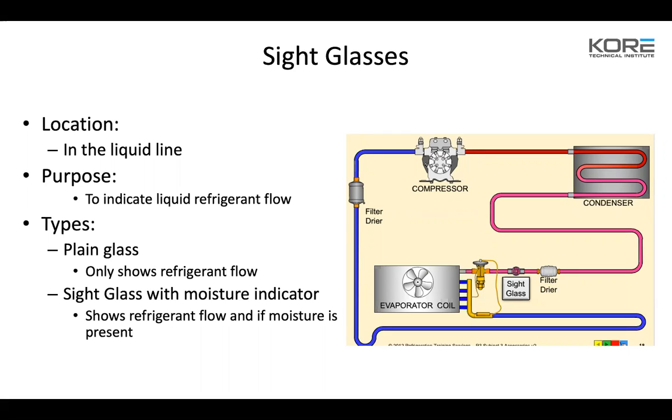So how's that liquid line going to feel if it's not condensing? It's going to be hotter. Yeah. So what your liquid line should always feel like is a little bit warmer than ambient. So the easy check to know if you're undercharged or overcharged: if you're undercharged, it's usually going to be a little bit cooler. If you're not condensing and you're not rejecting that heat and it's flashing and you've got flash gas going through there, then you're going to grab that line and it's going to be significantly hot, and it's not going to feel like it's condensing.